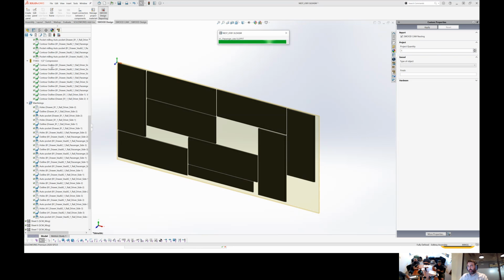So that's part of the strategy we can insert. We have the options to insert not only one contour, but two contours to create an onion skin strategy. We can add tabs between the parts as well. That's in the manual nesting. You can add bridges between the panels to keep the vacuum and some material between the small parts, for example. So yeah, we get these options.